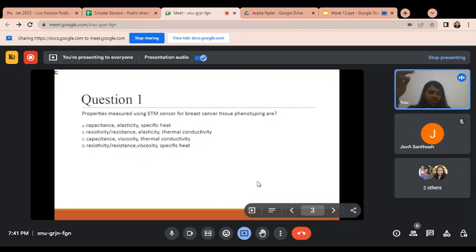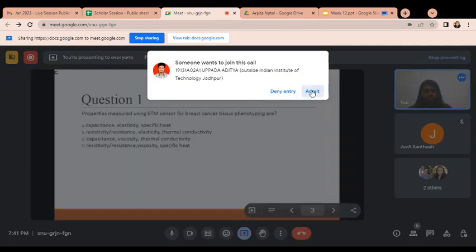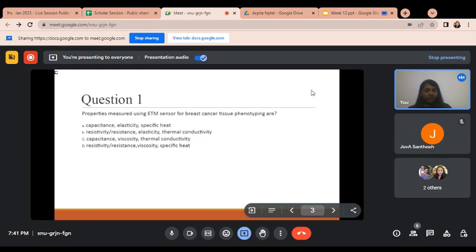so this portion is not directly coming into contact with the UV rays, so it will dissolve into the solution. When we dip the wafer into the developing solution, in that case this portion will be gone, but the portion of the photoresist coming into direct contact with the UV rays will stay. After that we do the etching, because the pattern is transforming from the mask to the photoresist layer.